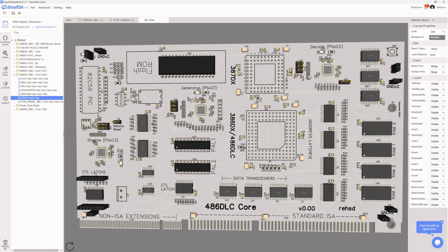That would just feed me power, ground, and then these three programming signals. And I might want to also add, I'll probably do this now that I think about it, two more pins for the power and ground, the VCC and ground, so I can completely pull these 5 signals from the entire board so that I can program this, and maybe that way it's not going to try to provide power to the whole board when I plug in the programmer. But anyways, that's what these pin headers would be for, just jumpers. So I need to make note of that.